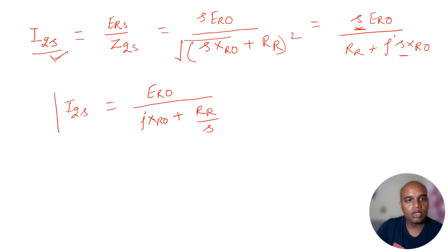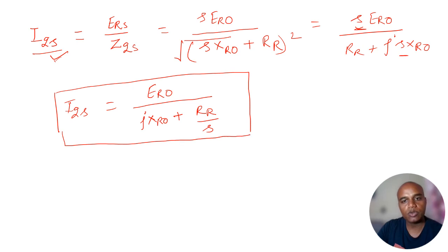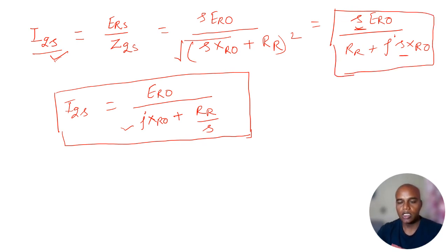So looking at these two things, we have two expressions for the rotor current. One is this one, the other is this one, and both are the same. Both will give me the same value. However, for my equivalent circuit diagram, I can say that my rotor induced EMF is just like the transformer approximation. The induced EMF from the primary circuit is the same as what I'm getting at the secondary circuit, if I take the voltage ratio as 1.